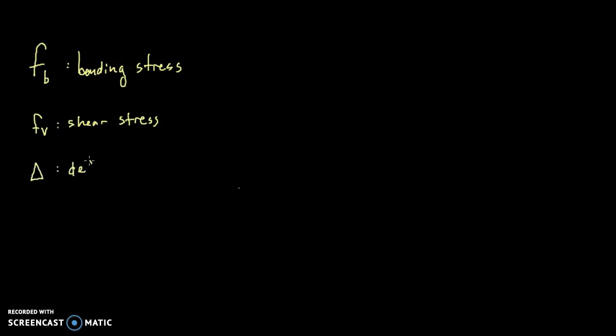We also need to make sure that the beam we choose is adequate to provide a minimum amount of deflection, or at least somewhat less than the maximum allowable. So we've got basically three things to check here: bending stress, shear stress, and deflection.